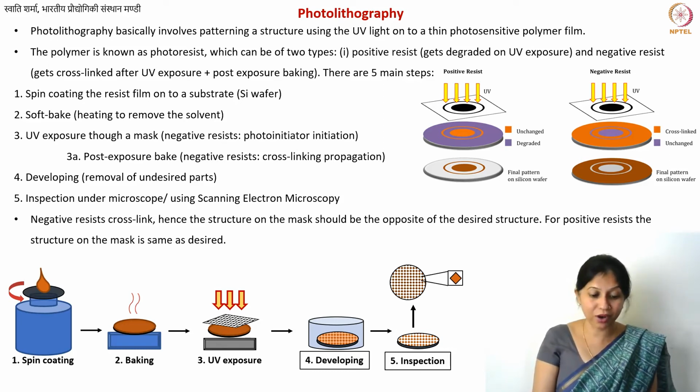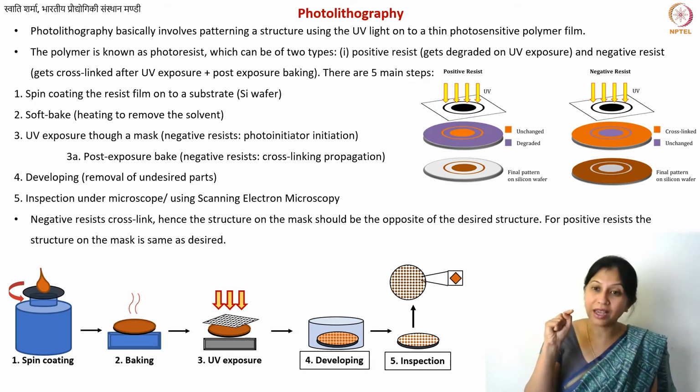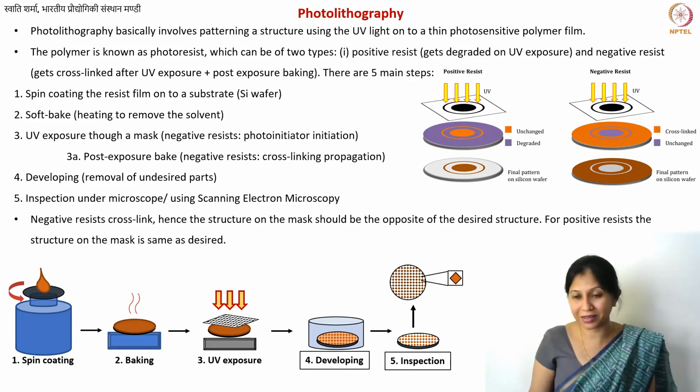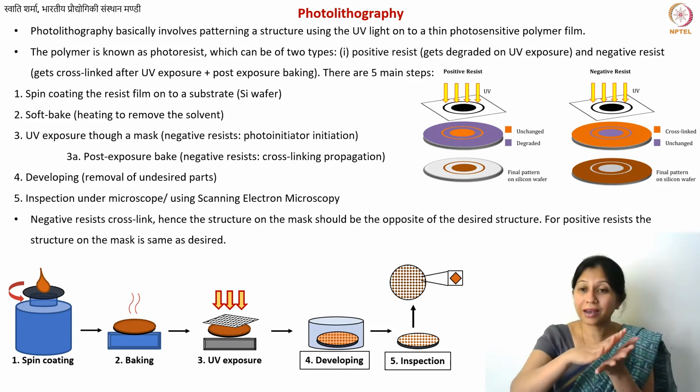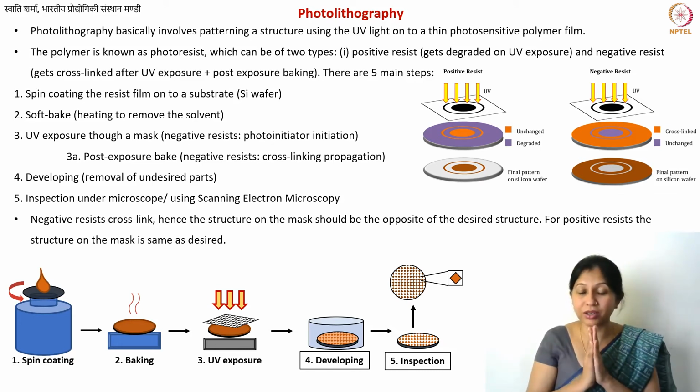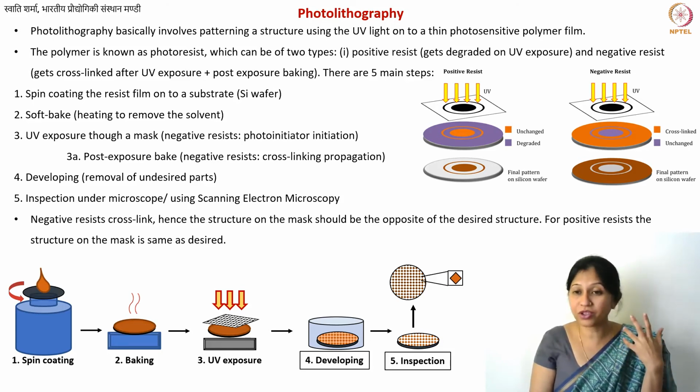But then, why do we talk about graphitic content in them? Well, some parts do have graphitic ordering. They may not have the ABABA arrangement, they may not have the exact graphite-like hexagonal crystal structure, but they do have these graphitic sheets on top of each other. They may be randomly oriented. Random orientation is known as turbostratic arrangement. So these are turbostratically arranged carbon structures that also contain some curved carbon structure.